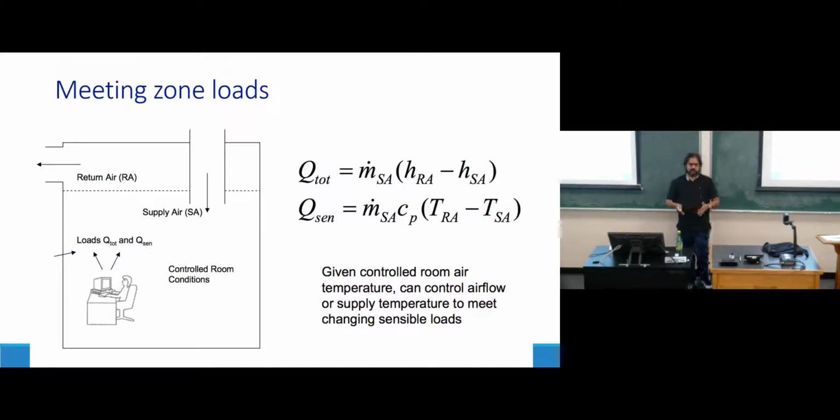The heat flow is the mass flow rate times some specific heat of the air times delta T. You can calculate the actual heat load or demand of the zone just by looking at the mass flow rate of the air, assuming it is constant, and looking at the supply and return temperatures and their differences. That's how much heat you have extracted away from the zone. And so we can describe it mathematically, and we'll use this property to actually build our state space model.